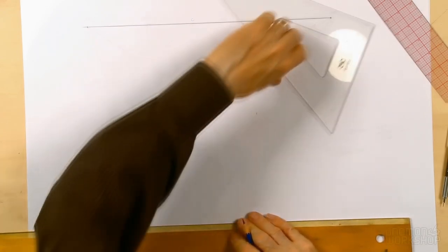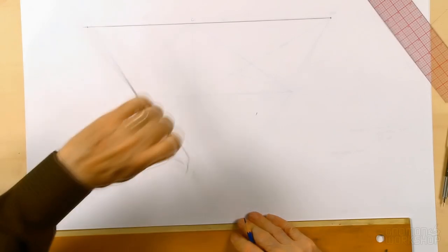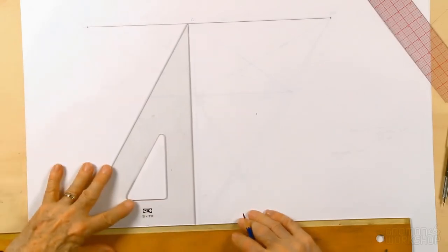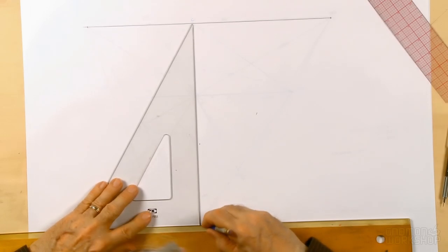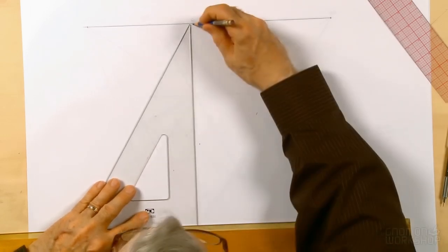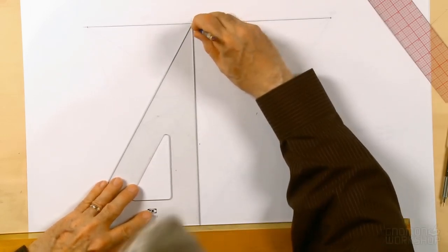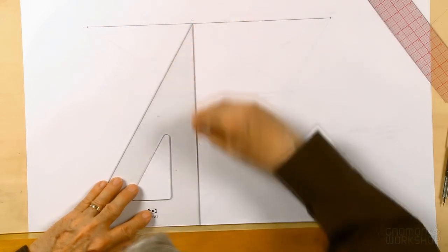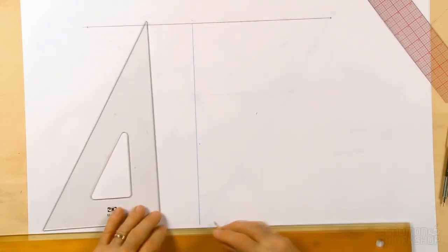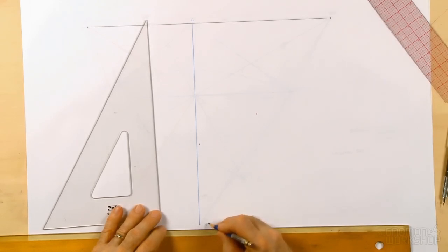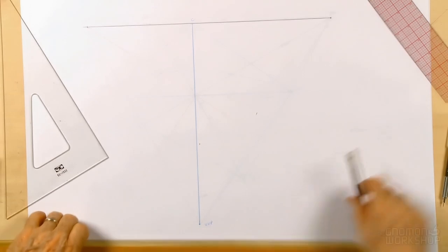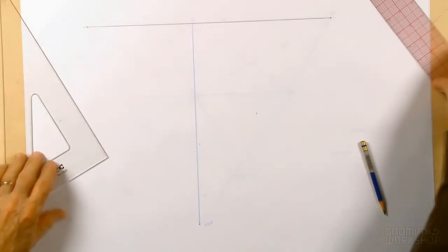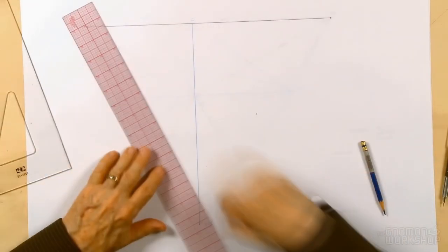So then drawing from there down in blue, what I'm drawing here is the vertical reference line, and it's going to come right down. It's at a 90-degree angle to the horizon up here, and it comes right straight down like this. Now on that line, I've picked an arbitrary vertical vanishing point, VVP, down here. Now that I have that, I have the three vanishing points located.